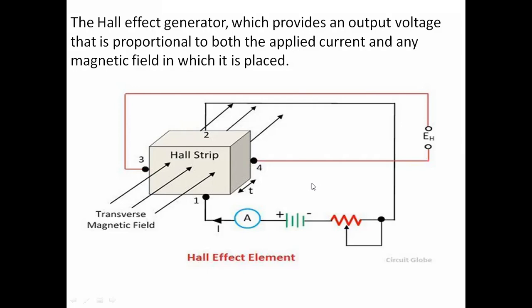So these are the passive transducers. If you consider the passive transducers, we have resistive, inductive, capacitive, and active circuit element types. In the resistive circuit elements, the main resistive elements are potentiometers, photodiodes, and strain gauges. In the strain gauges, again we have two types: metal strain gauge and semiconductor strain gauge. In the metal strain gauge, again two types: unbonded strain gauge and bonded strain gauge.